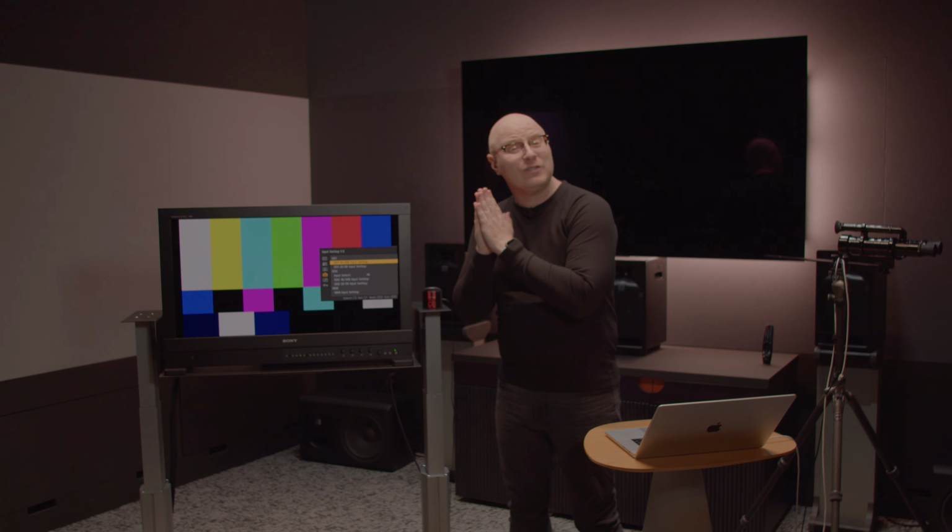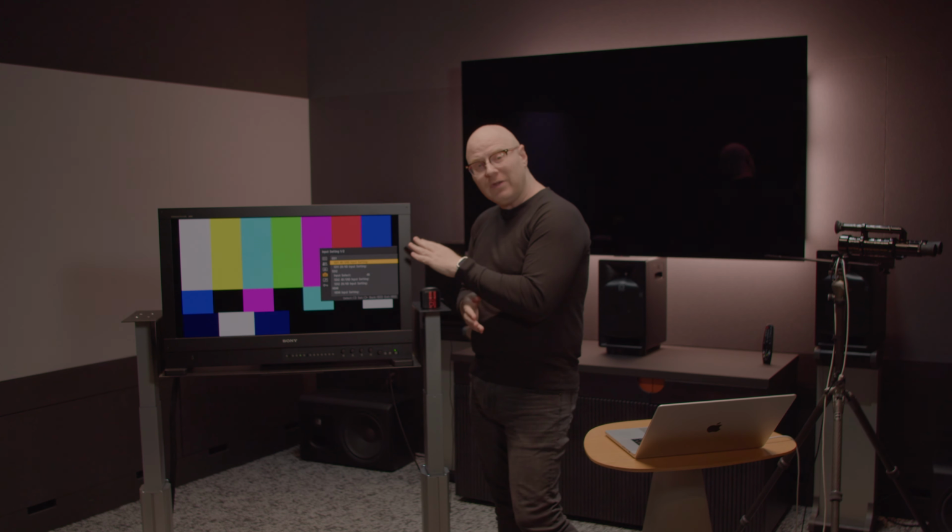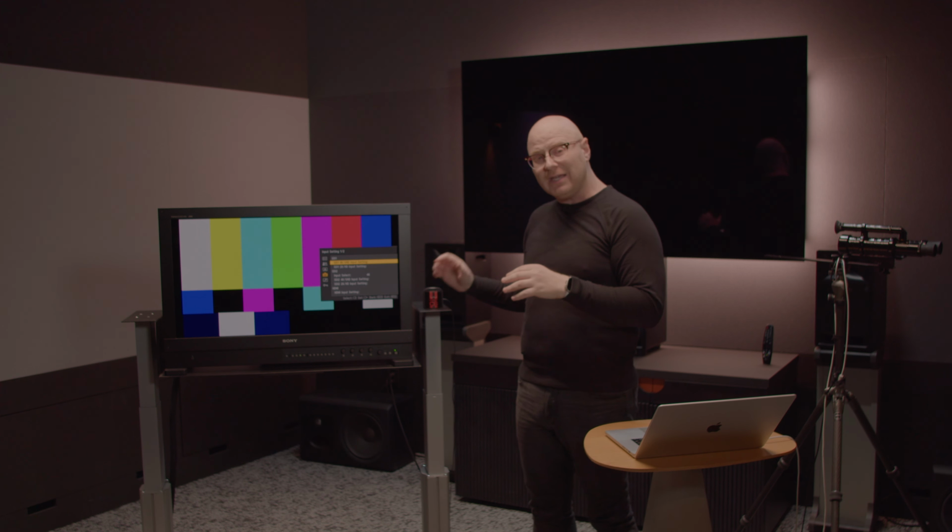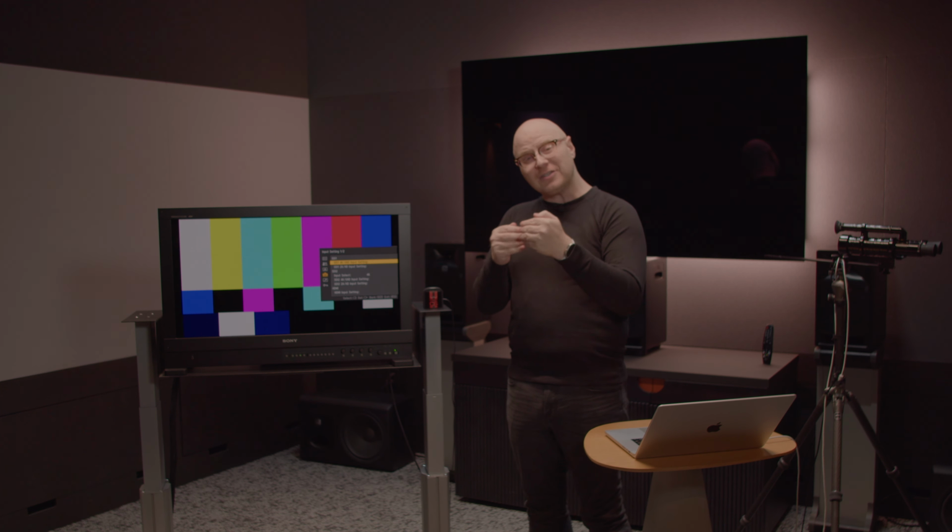On most displays that we calibrate today and we work with today, we don't have a separate calibration setting between, let's say, 1920 by 1080 content and 3840 by 2160 content. We usually have one calibration, and that applies to both. So with the Sony here, what they're giving us is the ability to say, hey, when I'm sending 1920 by 1080 content, I want the display configured to X. And when I'm sending 3840 by 2160 content, I want the display configured to Y. That way, a user can actually change the calibration of the display just by sending it different content.